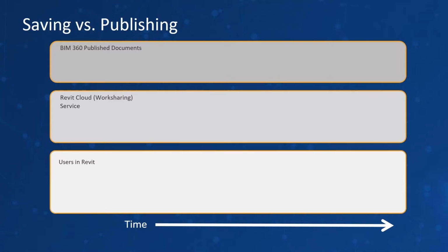It means that we can view DWG, DXF, but also other file formats such as DGN, IFC, SketchUp files, etc. And that's the quite critical part here: as I mentioned, you don't need anything local on your machine. No Design Review, no DWG TrueView or anything, or even Revit in demo mode or whatever. You can just use that viewer and understand those files.